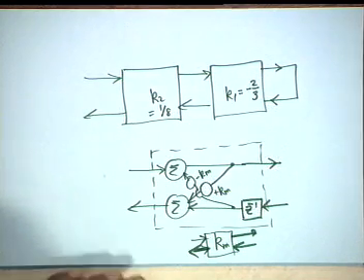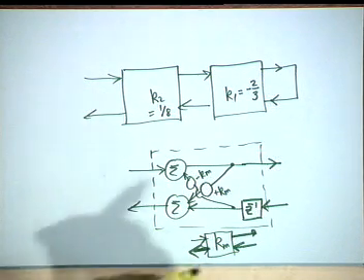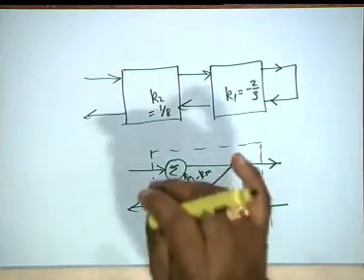It is modular. This modularity leads to simplified fabrication in VLSI. If there is a structure which requires a processing step change at every step, it becomes a very costly proposition. On the other hand, all that you have to change in the processing is the value of K for each stage, and therefore it is a suitable thing for VLSI implementation. All right.